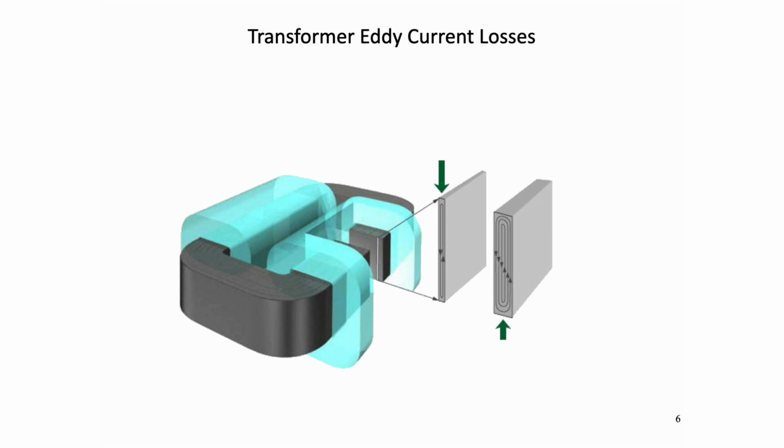The result of all this insulation is that the unwanted induced eddy current power loss in a core is greatly reduced, and it is for this reason why magnetic iron circuits of every transformer and other electromagnetic machines are all laminated. Using laminations in transformer construction reduces eddy current losses.